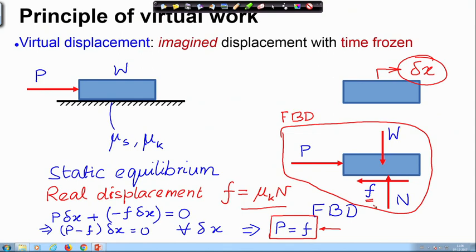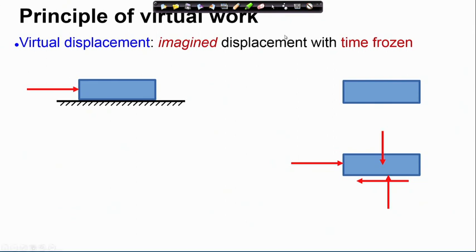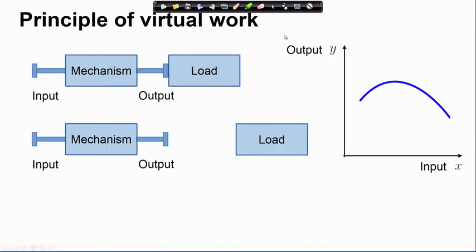But in the case of virtual work, when we apply the principle of virtual work as I have done here, we need not draw the free body diagram, as I will show you. We just need to have the input force, output force, and the displacements at the input and output, and the internal forces need not be considered. So, here again I explain the principle of virtual work for a mechanism that we are going to use.